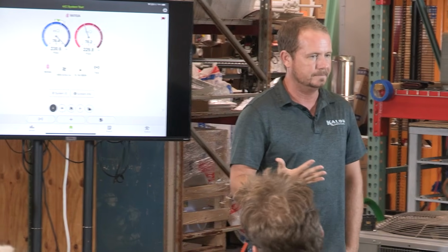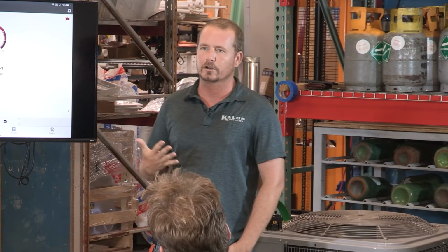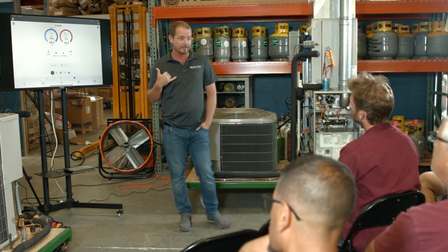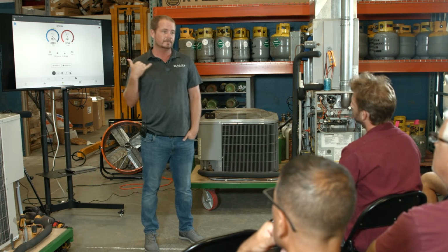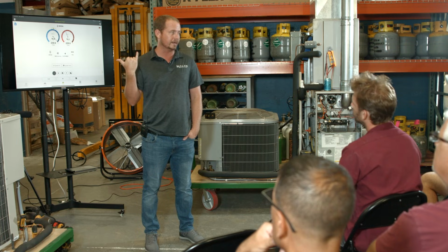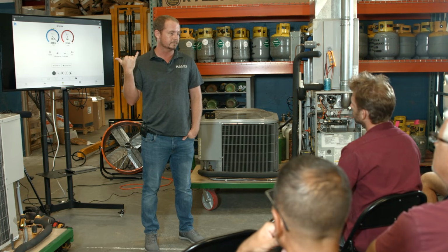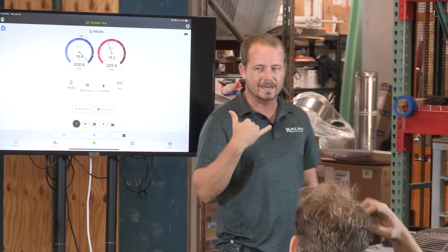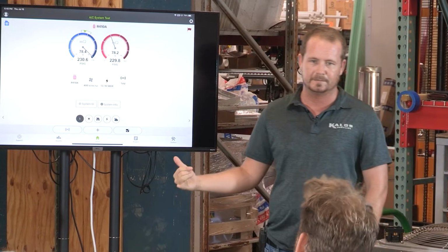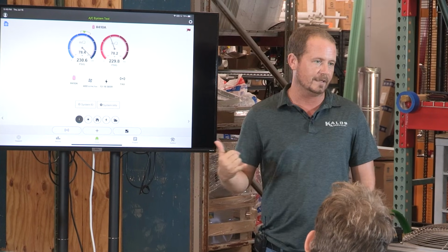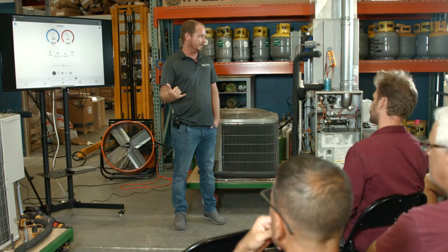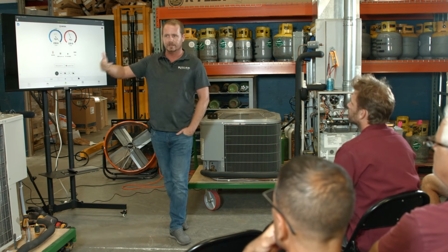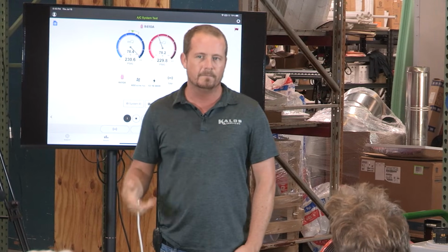And when they get done, a lot of technicians are going to call their manager or supervisor and say, I don't know what's going on with this system because I checked the airflow and it's fine. Right? Did you check the airflow? If you didn't, it wasn't fine. You did because you connected tools to the system that gave you every indication that airflow was not fine. Right? They're telling you that it's not fine. But what do you do? You go through your list, and then at the end you say it's fine. But did you measure airflow?